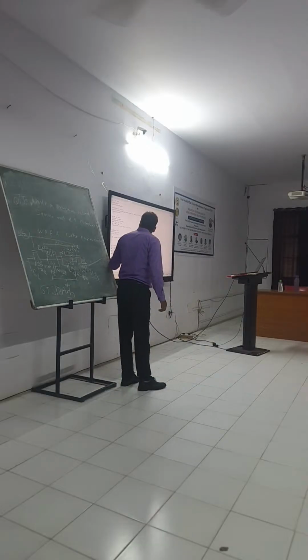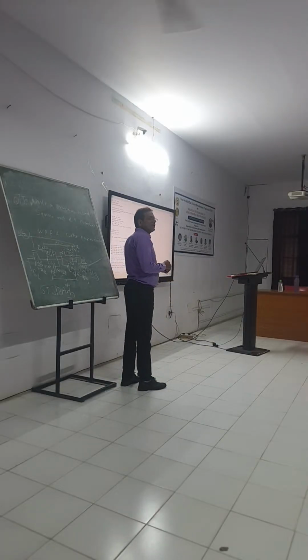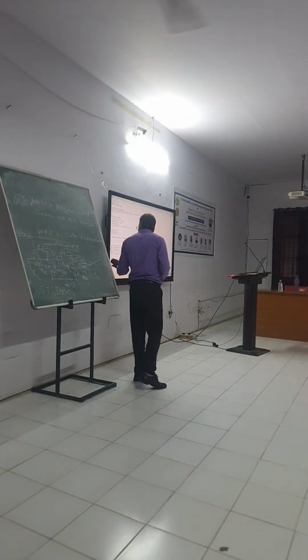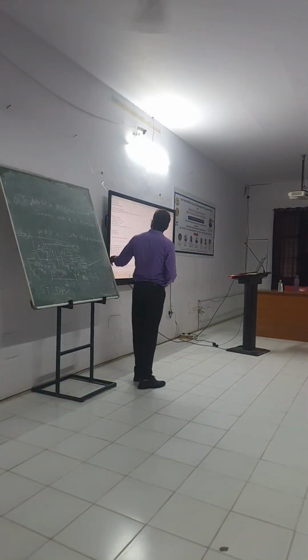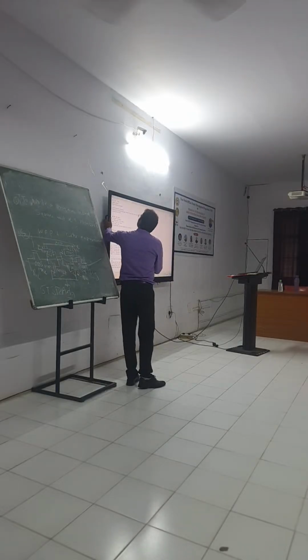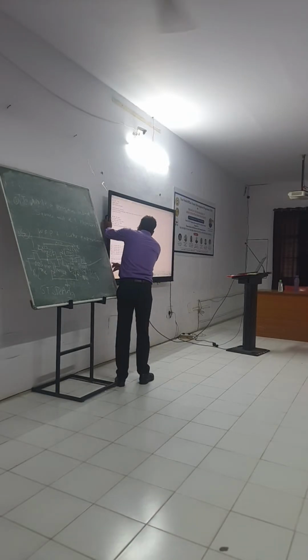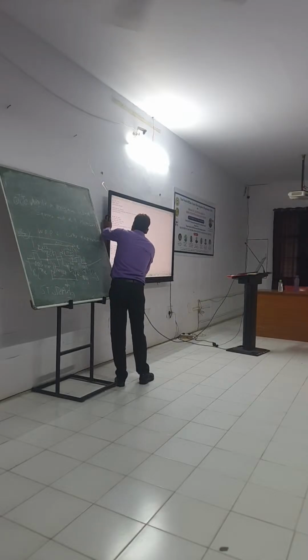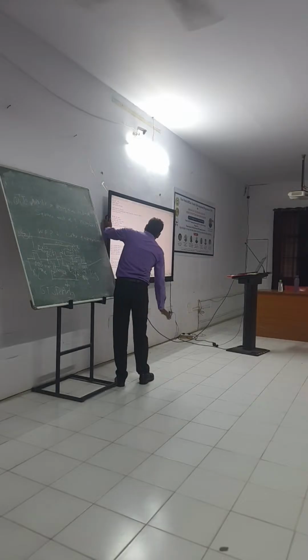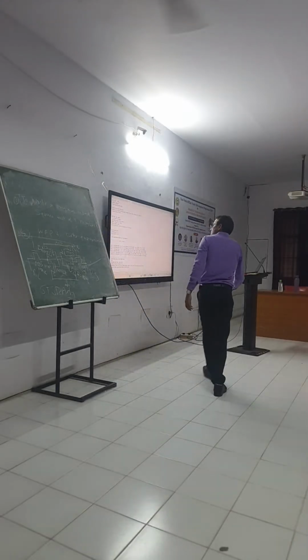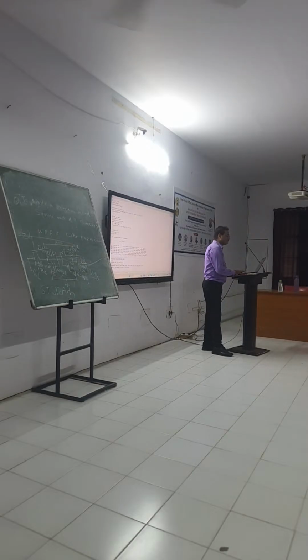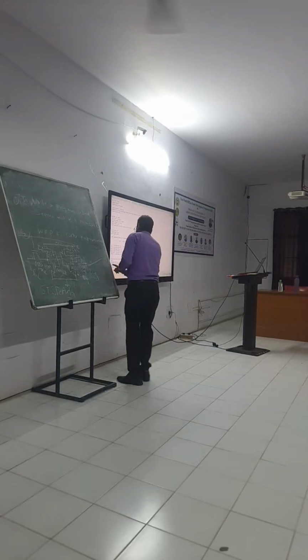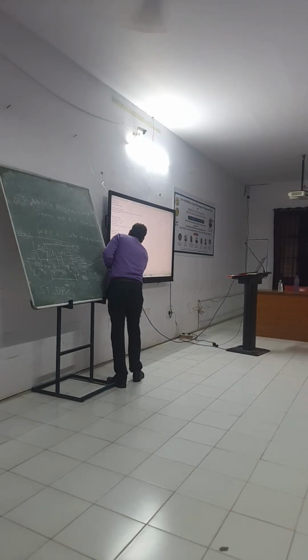See, the dot measure command we are using. The star one is commented, so remove the star. Then you can measure. Sorry, here it is commented, no need for this. See this one, measure TRA. TRA means suffix, so we are going to measure the read access time.